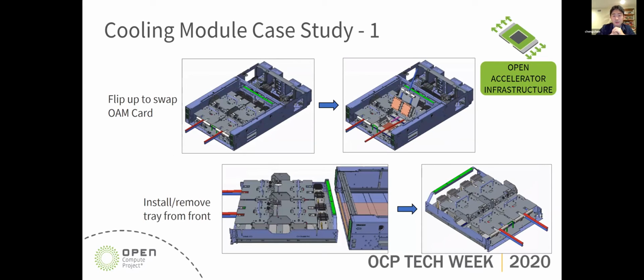This shows a service condition for the passive cold plate loops. Imagine one of the OEM cards is broken and you need to replace it. In the heatsink scenario, it's very easy. You just treat it together as a heatsink with screws. You remove 4 screws from the baseboard and you take it out. You add the new assembly, and that's it. But for a system with cold plates mounted, because the cold plates are attached to an external loop, you cannot remove them as simply as that.